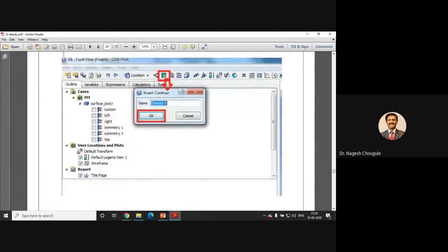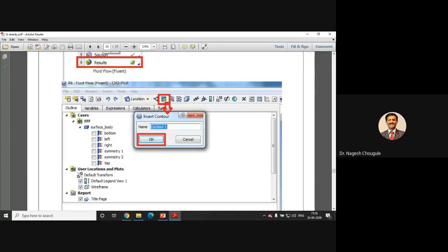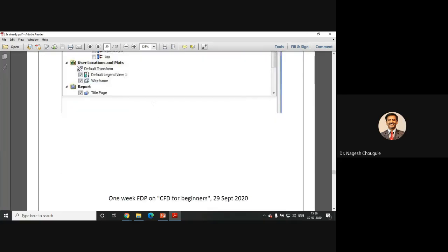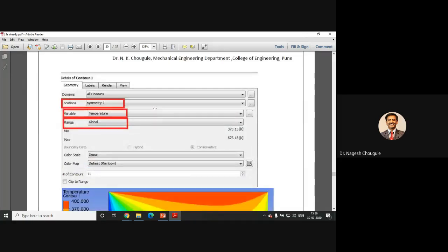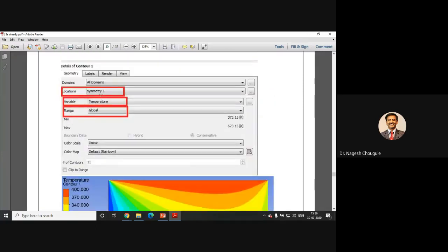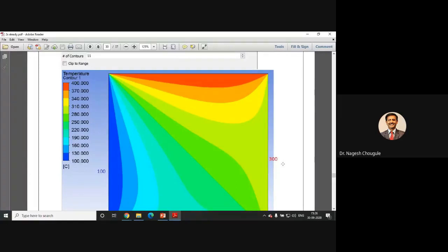Where you can see at the top the various contours. So this symbol is for seeing the contours. You can click on the contour and give an appropriate name also. For example, I can give Case A here, and then click on the OK button. Here we can apply symmetric boundary conditions also. With the help of symmetry boundary conditions, suppose this is the portion where I can do only half portion simulation and then reflect the images.